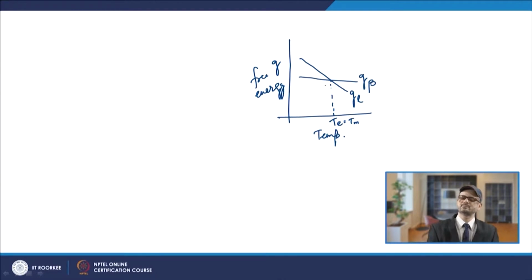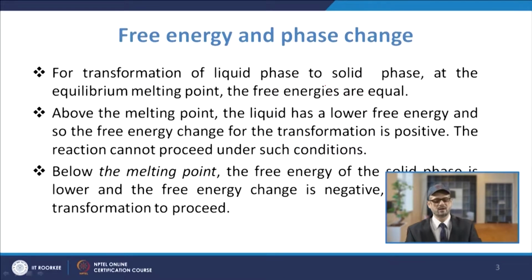So, that is why once you have a temperature less than the melting temperature, the transformation proceeds from the liquid state to the solid state, and that is the essential mechanism of determining in what phase the material will exist at any temperature. Now, what we need to know is the mechanism by which this transformation occurs. That is the mechanism of nucleation and growth.